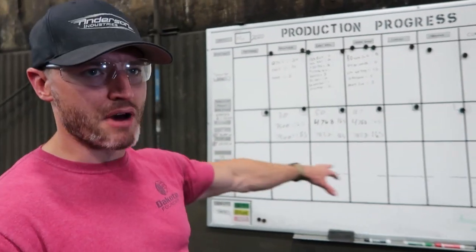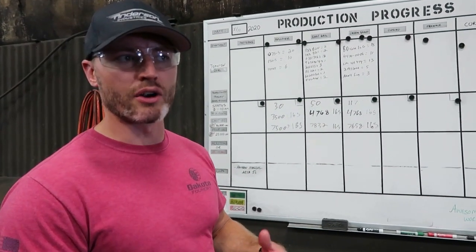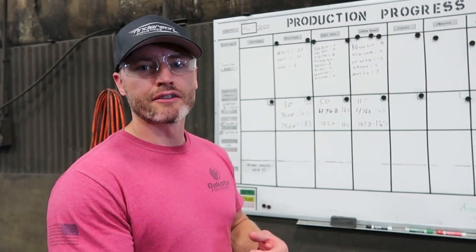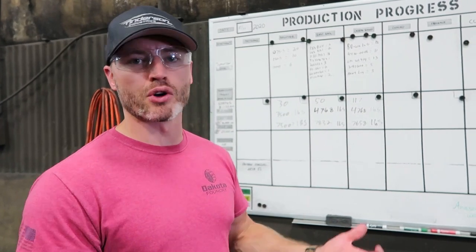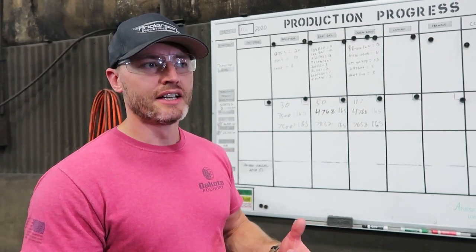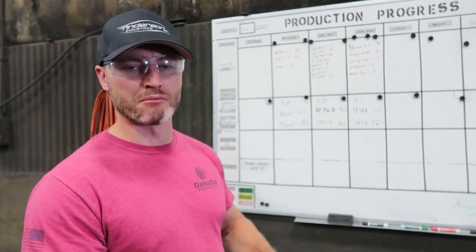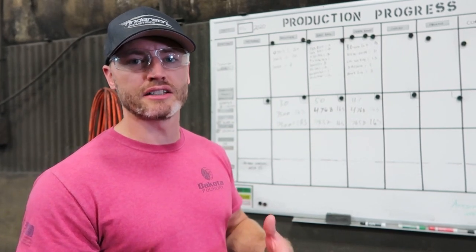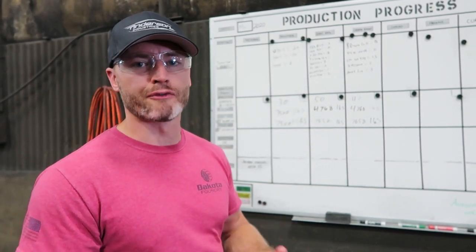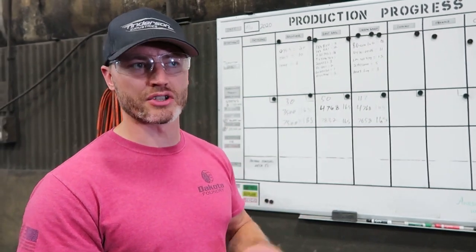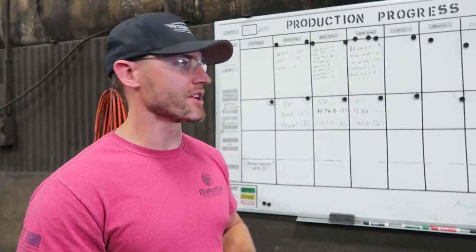And then at the bottom we have any additions or quality remakes or issues that we have to communicate. If there's a part that gets scrapped in grinding, for example, because a vent broke off into the casting, then they can add that right away onto this board, and the molding team will recognize that immediately and can remake another mold before we disassemble the tooling and get the tooling hauled back out to the warehouse. It's just a way to expedite the communication for those types of situations.